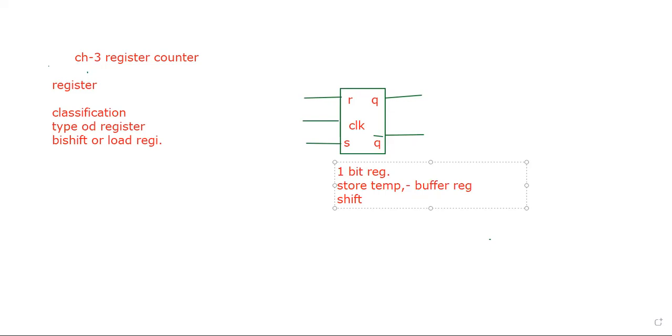And the next one is for shifting data. We have left shift, right shift, serial shift, parallel in, parallel out, different kinds of shifts. So this is the basics about the register. Suppose I want a 4-bit register, then it would be a combination of 4 different flip-flops. Understand? We have a 4-bit register with the help of 4 flip-flops. So as the number of bits increases, we need to increase the number of flip-flops.